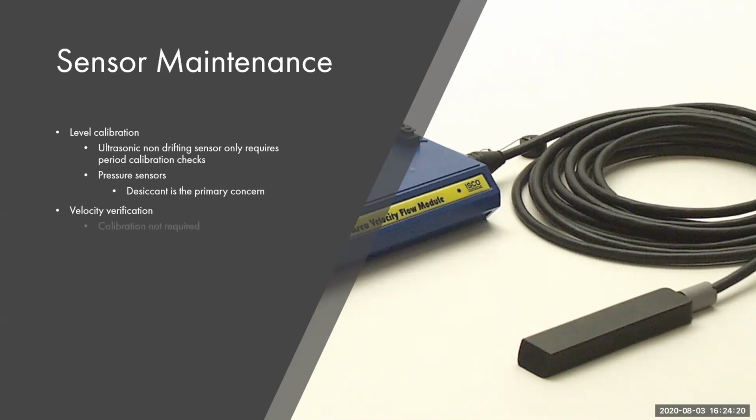Velocity verification, again, could be verified by a third-party profiler. Calibration is not required, but more importantly, taking a look at the advanced diagnostics that are available for those various velocity measurements will build your confidence in the quality of that velocity measurement.